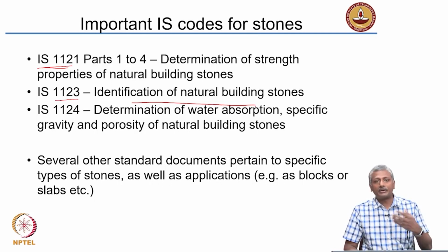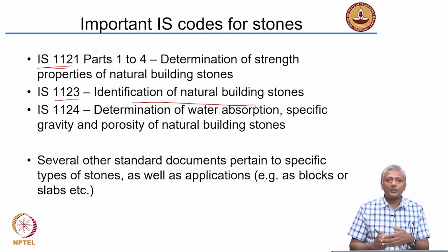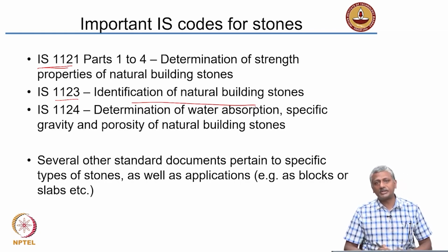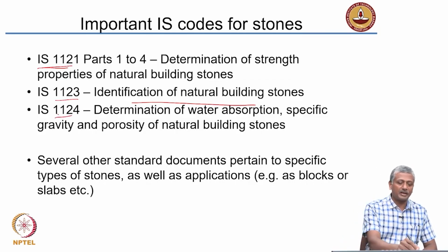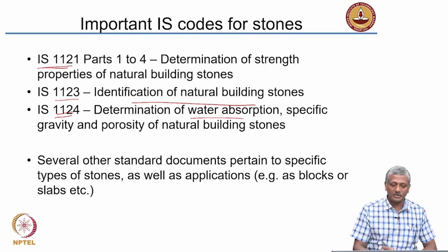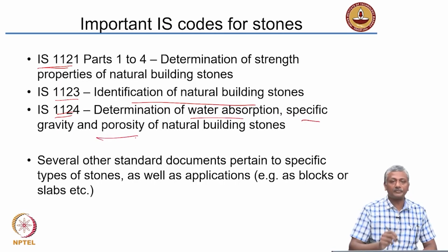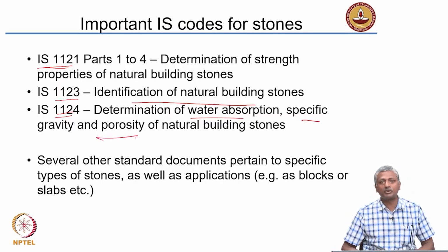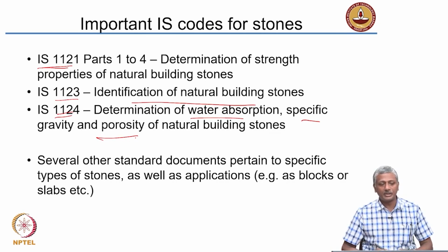Depending upon the mineralogy, depending upon the mechanical properties and so on, it gives you very clear-cut methodologies to identify what type of stone you are actually having for your construction process. And then of course, the other test parameters are water absorption, specific gravity and porosity. Those are also very important from the point of view of engineering applications of the stones. So that is covered in IS 1124.